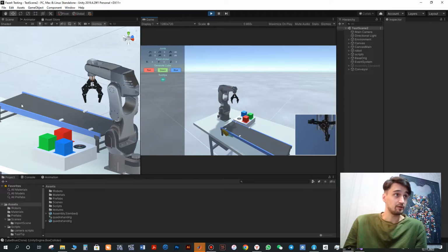So here we have a conveyor with an object moving along it, and here we have 2 sensors. Firstly, we will change the speed of the cube to the slow one, and here it will be stopped. In an automation system, these 2 sensors are usually used for more precise positioning of the cube in the place where the robot wants to grab it.